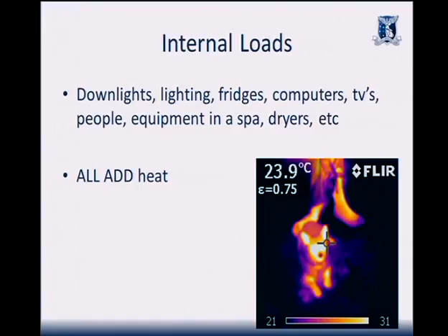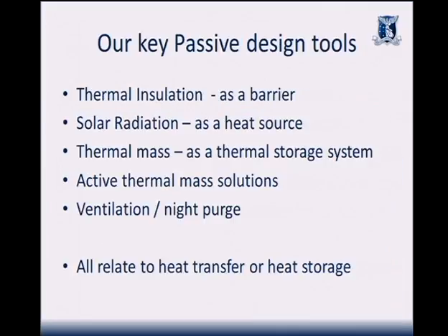So you need to allow for that. This is all, how do you piece together the puzzle to create the right house? Because one apartment with 8 people in it is going to be hotter a lot more of the time than the same apartment with 1 person. And that means the strategy that you need to use to reduce energy is different. So I guess that's the key aspect of this section, that you need to understand the needs of the space to determine what's the right design. And that is quite hard early in the design stage.